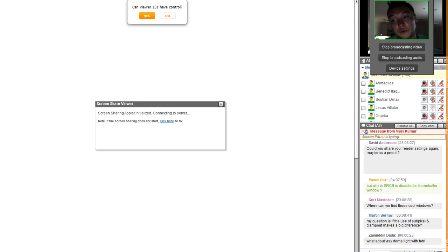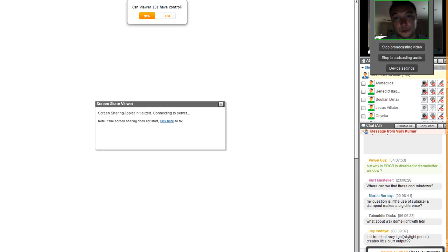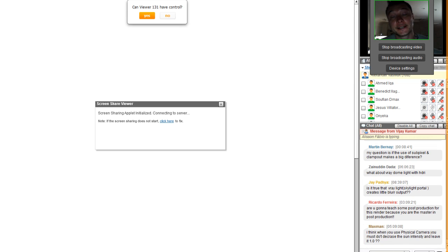And if you use clamp, it just cuts it out and doesn't give you the depth. If you want to have the depth and recover the information, if it's overexposed or underexposed, you can render HDRI, or you can render OpenEXR, which is floating point, and save that image and work with it. But in that case, you don't need to activate the clamp output option.